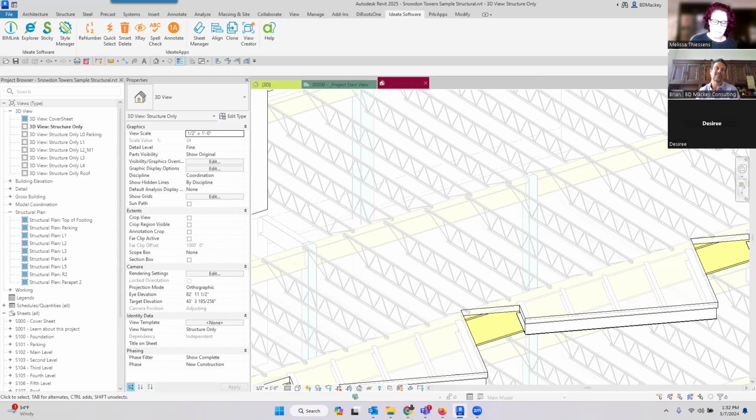But if that material resides within the project and you try to copy something from another project that has that material loaded in, or load a family that you've made changes to that same material and bring it in, Revit will not overwrite the materials in a project when something else is being loaded in. If that name exists, it rules within the project. So you're not going to be able to get that to happen.